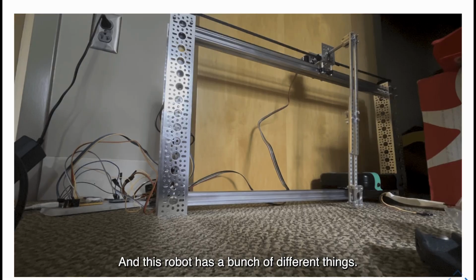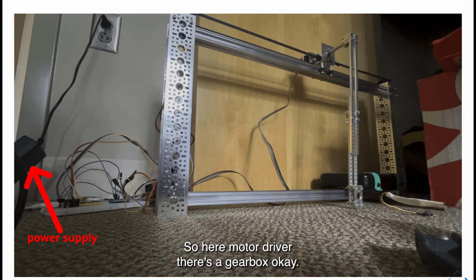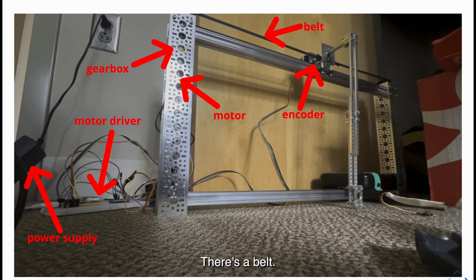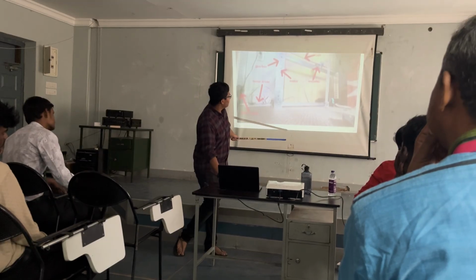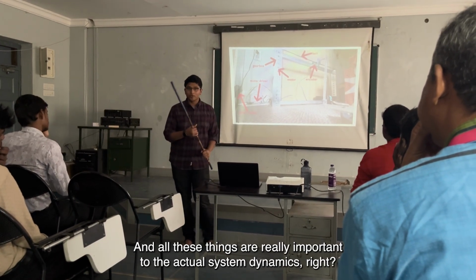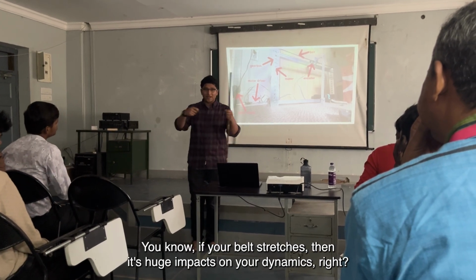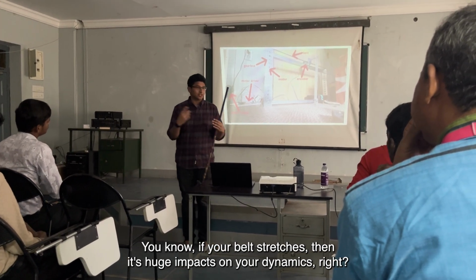And this robot has a bunch of different things. It has a power supply down here, motor driver, a gearbox connected to a motor, an encoder up there to track the angle, and a belt. All these things are really important to the actual system dynamics, right? If your belt stretches, that has huge impacts on your dynamics, right?